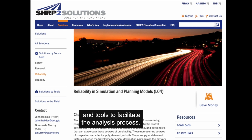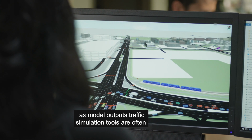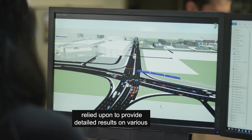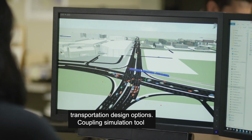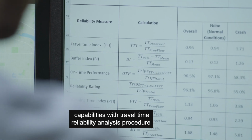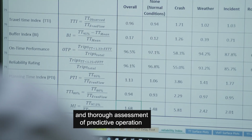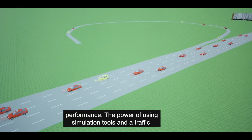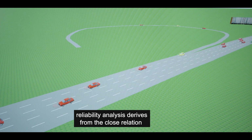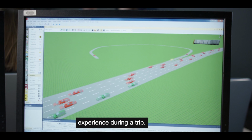Because of the availability of vehicle traversal times as model outputs, traffic simulation tools are often relied upon to provide detailed results on various transportation design options. Coupling simulation tool capabilities with travel time reliability analysis procedure provides decision makers with a highly detailed and thorough assessment of predictive operation performance. The power of using simulation tools in a traffic reliability analysis derives from the close relation of the output data to what travelers actually experience during a trip.